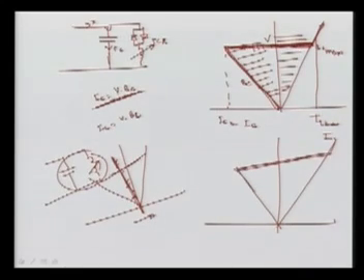So the characteristic is not 100% horizontal; we provide some slope, and this is basically called the natural regulation, and it is due to the transformer which we connect. If you remember, here it was the transformer, then we have the SVC here. So this impedance is there, so for the current which is flowing here, there will be some drop, and there will be some slope here.